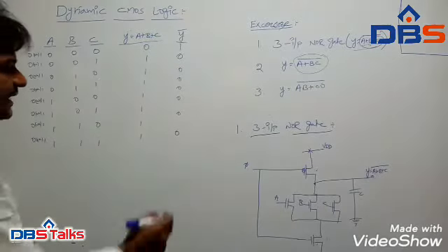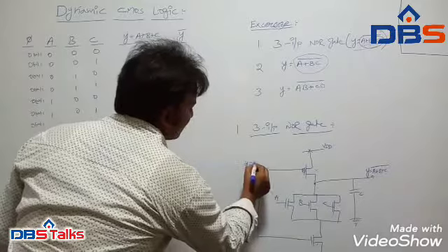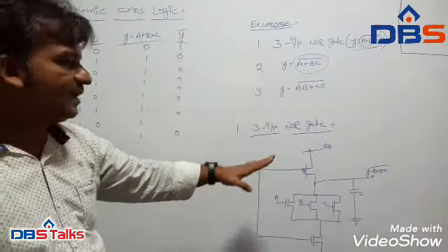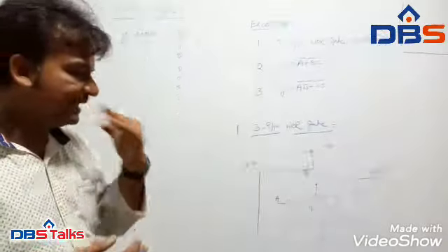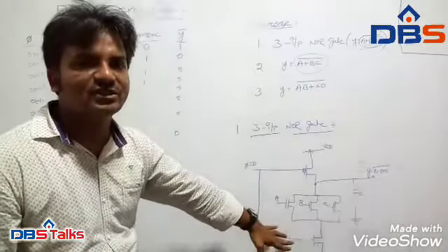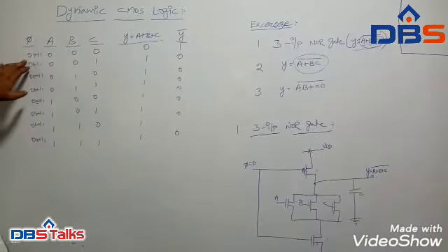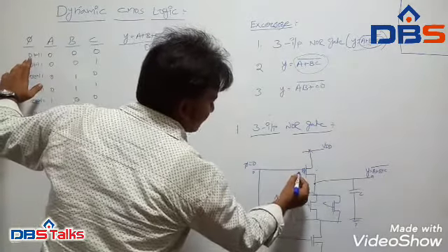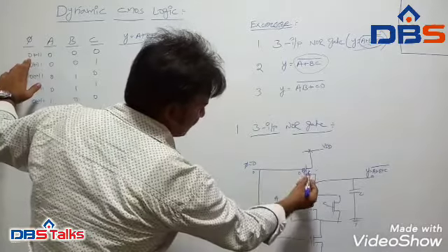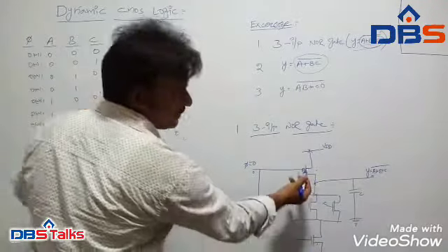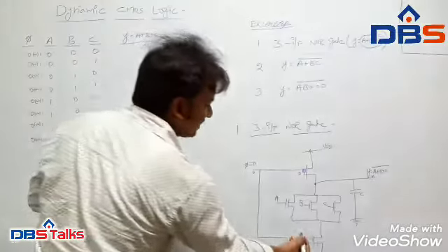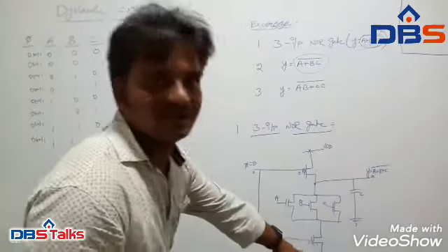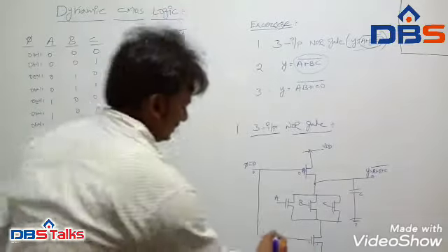So here coming to case 1, first case is pi is equal to 0. So we are applying pi is equal to 0 or 1 to operate in a specific mode of pre-charge and the evaluation mode. So if pi is equal to 0, in that case, for both transistors, that is the p-type and the n-type transistor, the pre-charge transistor and the evaluation transistor, the input is 0.